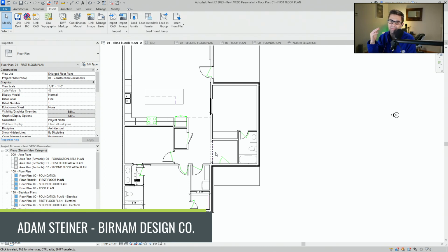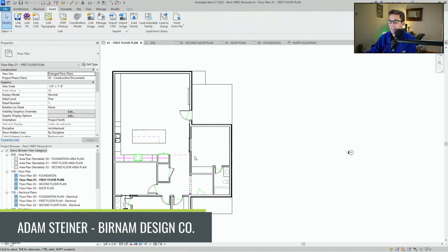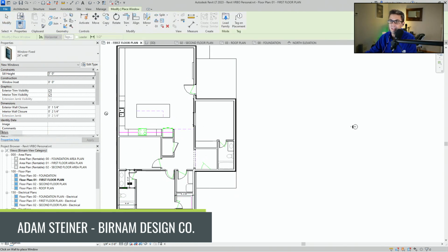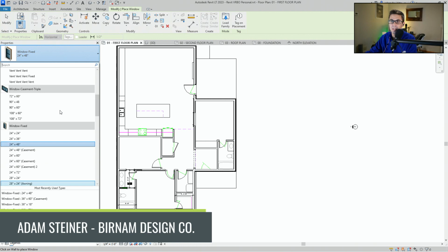And yeah, rough openings are available online, but again, the window supplier might spec something slightly different or like a different line than what you had in mind, and that 1/2 inch can really screw things up. So it's a little bit easier to do by centers. And then you have less things that you're wanting to change later.